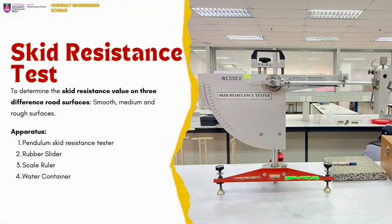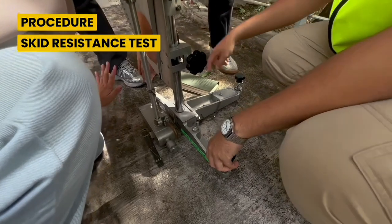The first test is the skid resistance test. The objective is to determine the skid resistance value on 3 different road surfaces, smooth, medium and rough. The apparatus needed is a pendulum skid resistance tester, rubber slider, skid ruler and water container.